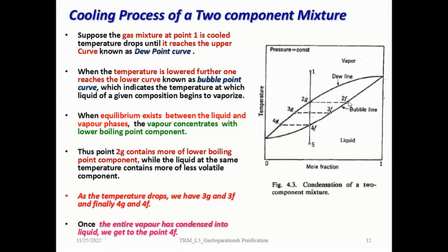You cool it further, then as the temperature goes down, the gas phase enriches more in the low boiling component, and the liquid phase enriches in the high boiling component. Again, as you go further in temperature and reach, let us say 4F, then all the gas is probably totally condensed, but the gas phase has further enriched in the low boiling component, whereas the liquid phase has enriched in the high boiling component.